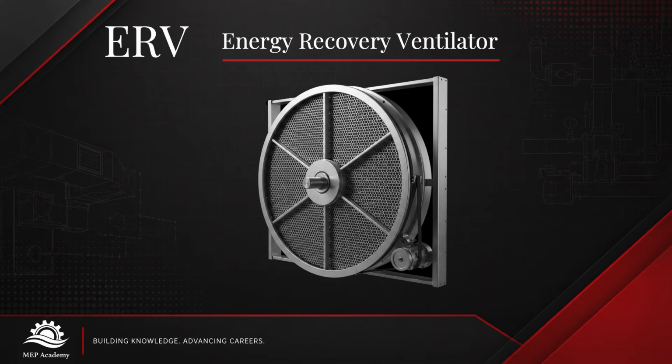Number 6. ERV, Energy Recovery Ventilator. An ERV provides ventilation while transferring both heat and moisture between the outgoing and incoming air streams. This reduces heating and cooling loads while bringing fresh outdoor air into the building.